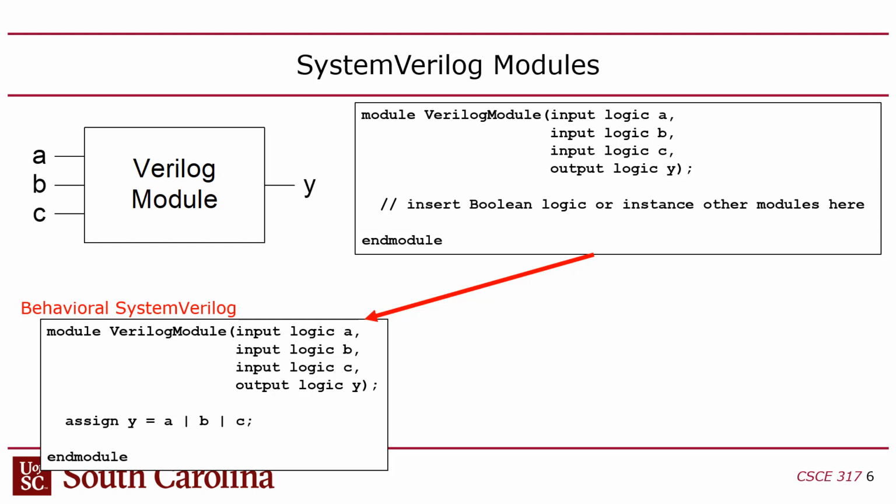But the last time I tried that, it blew up. I literally just said A divided by B, one line of code, and it used up the whole FPGA, because I was trying to do a combinational divide, not a pipelined divider and not a multi-cycle divider where hardware can be reused, but a divide in one clock cycle. That's death, right? It's very expensive, because all the shifts and subtracts and restores would have to all be done in a big circuit.